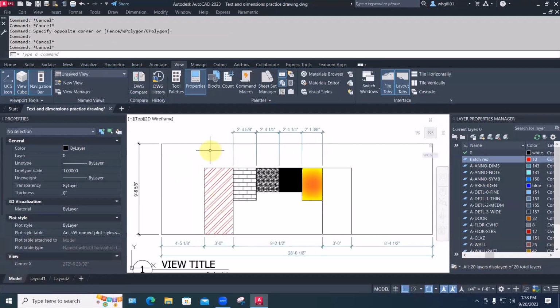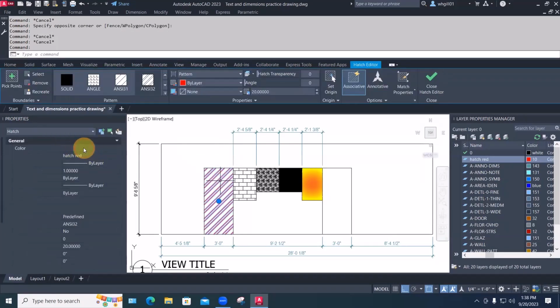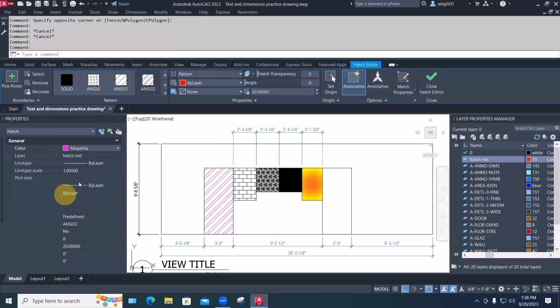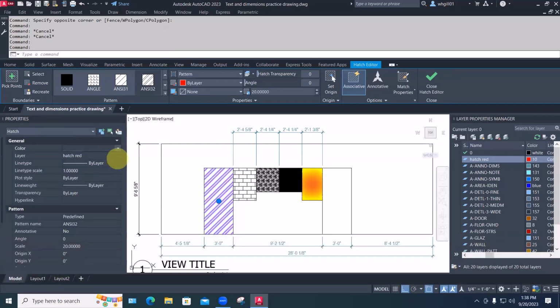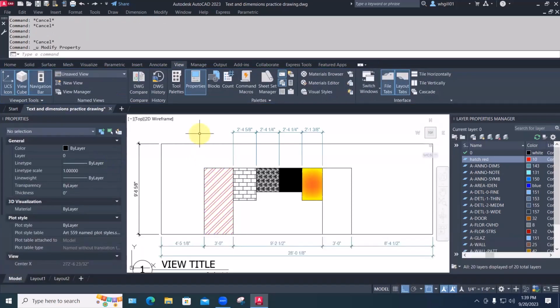And again, you really don't want to be putting it on a layer that's named hatch red and then change its color independently to magenta or something. You're turning things on and off and you can't tell what they are anymore. So we'll Control Z and leave that back on the red layer. So in that respect, they behave just as if they were that many lines drawn.